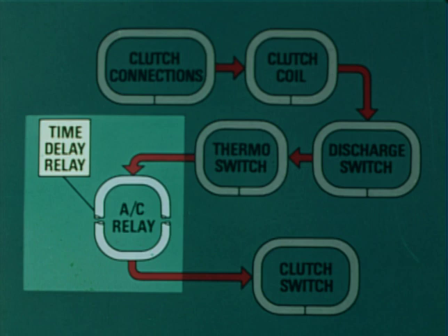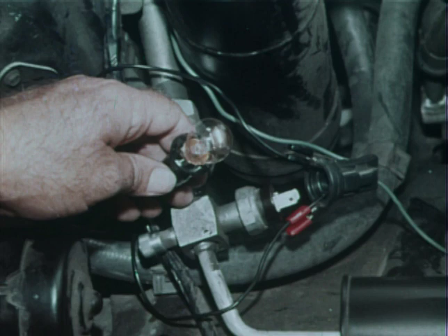The one exception was the time delay relay. Its function is to hold the AC relay open for 20 to 25 seconds, and he tested it simply by removing its connector. In the rare event that two or more components are defective at the same time, it would not be possible to locate the problem by bypassing each component as we have outlined. In this case, it would be necessary to use a test light to trace the voltage from the fuse block to the first open point in the circuit. Once this open has been corrected, the circuit is checked further until the second defective component is located.